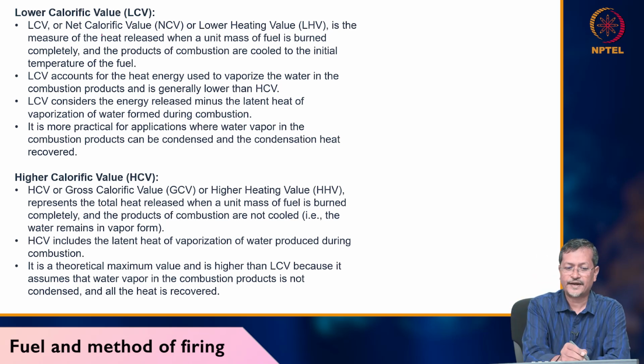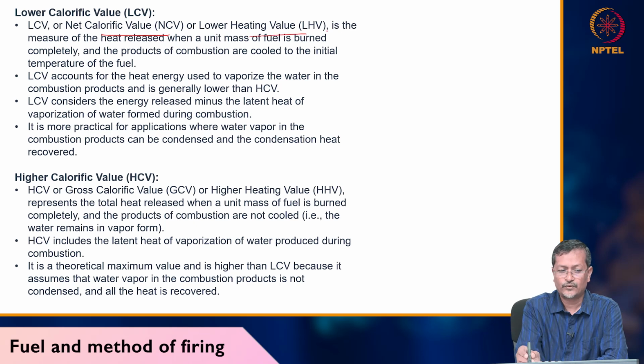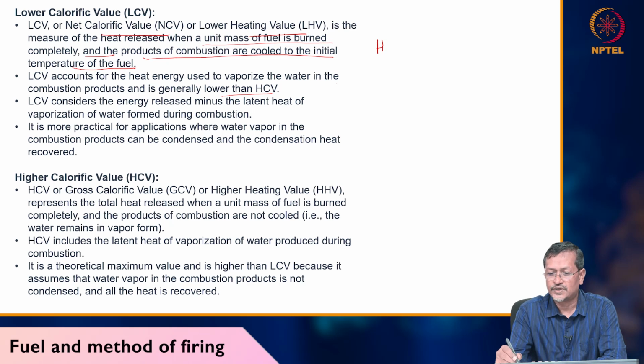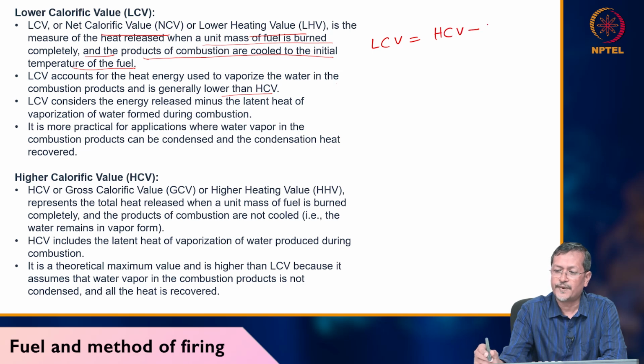Lower calorific value, or net calorific value, or lower heating value, is the heat released when unit mass of fuel is burnt completely and the products of combustion are cooled to the initial temperature of the fuel. LCV accounts for the heat energy used to vaporize the water in combustion products, and it is generally lower. So LCV equals HCV minus some heat.